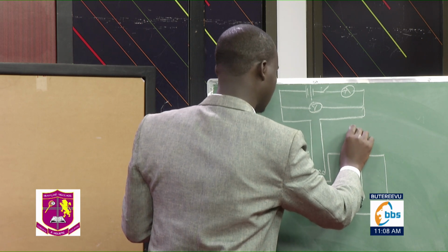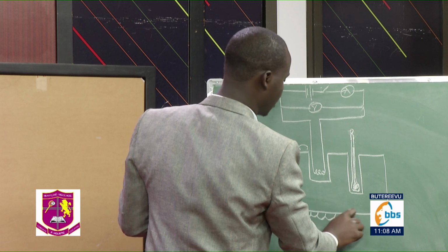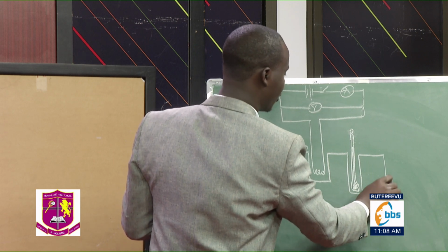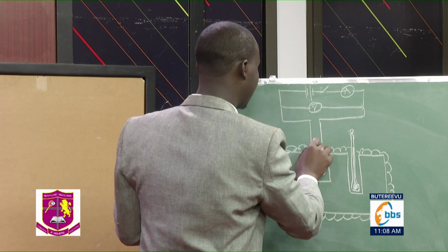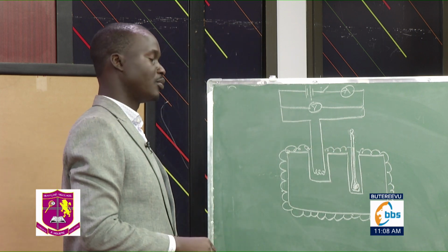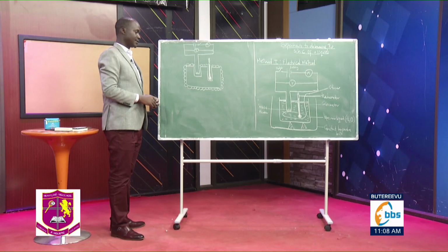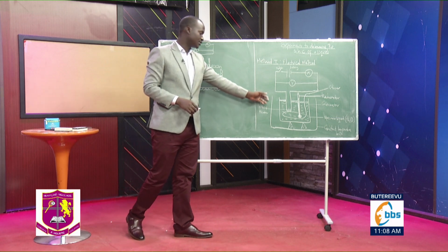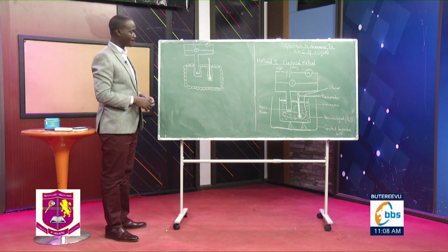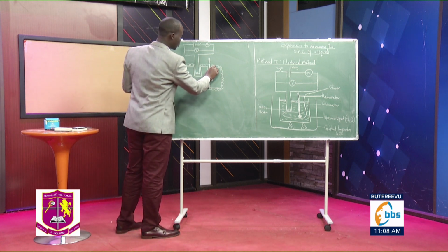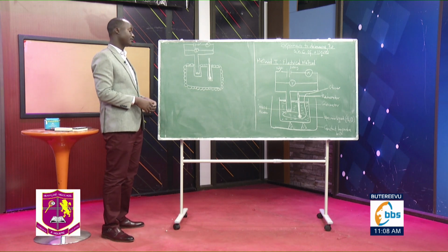So, what is the purpose of the lagging? I'm trying to ensure that I prevent heat losses to the surroundings by radiation in this case. Even here, I used the constant temperature bath in order to control that heat which could be lost to the surroundings, since in the final calculation, I do not account for it.